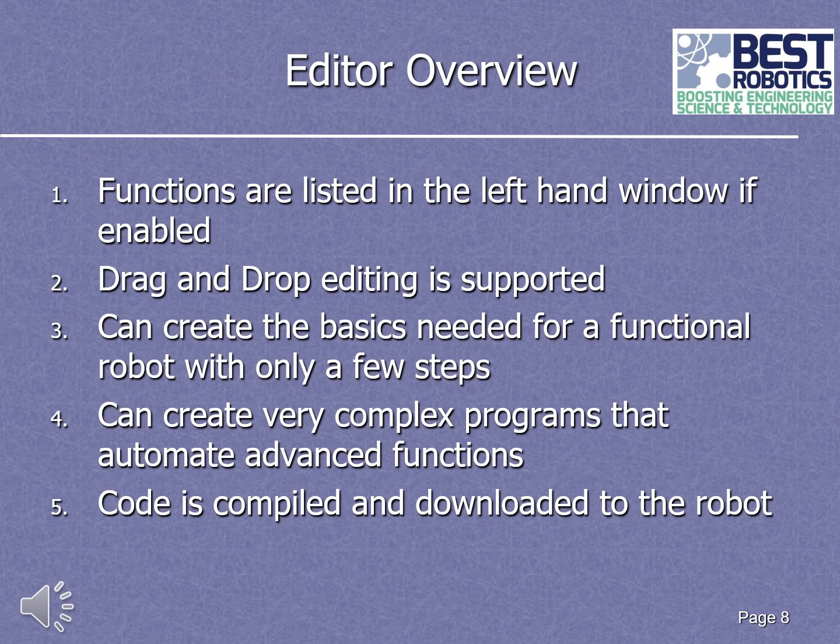The editor with RobotC has several panes, and on the left-hand side there are functions that you can explore. You can drill down into function definitions, and then if you find a function that you want to bring into your program, you can drag it out onto the text window. On the next slide, you'll see an example of the while loop being dragged out and placed in the text window, which saves you a little typing. The key there is the ability to drill down and see all the different functions that are supported by the IDE.